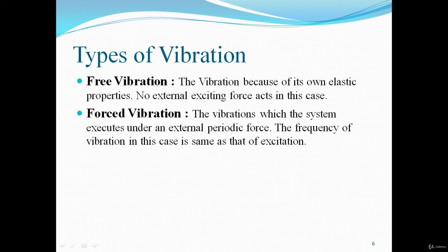First one is free vibration, right? When the vibration is caused because of a component's own elastic properties, with no external factor involved, this sort of vibration is called free vibration, right? So natural frequency has very much influence in this sort of vibration. And as we are saying it, that means to analyze the free vibration condition, we need to determine the natural frequency of the system, right?